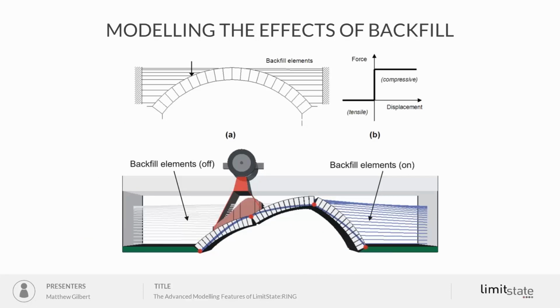One thing I haven't mentioned that's important in a masonry bridge is the presence of backfill. So backfill surrounds a masonry arch element typically, or very commonly, and the way we model this in the software is quite simple. We don't model it directly, we model the anticipated effects. So the effects are to distribute the live load, or disperse the live load, to provide vertical self-weight loading onto the arch, which effectively pre-stresses the arch and provides it with more resilience to movement.